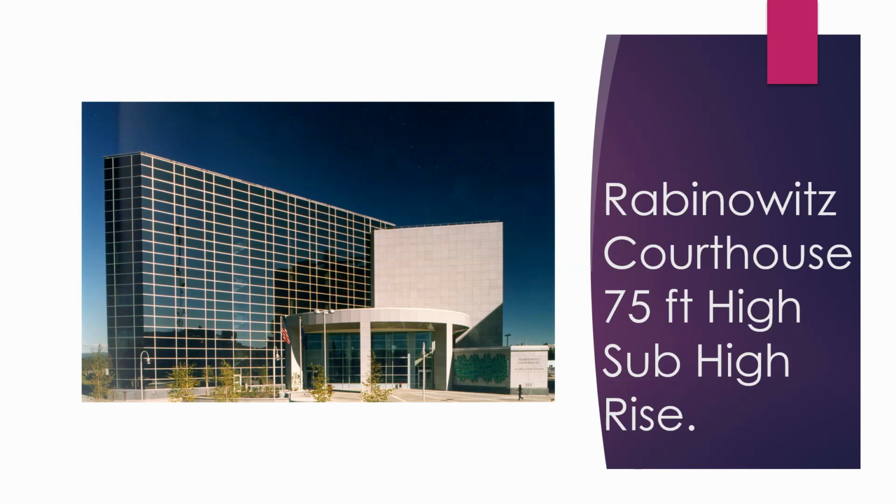At the entryway, there is a security guard just outside the entry who, if there is significant infiltration, is subject to that infiltration. So on a minus 50-degree day, that security guard is in trouble if we have significant negative pressure.